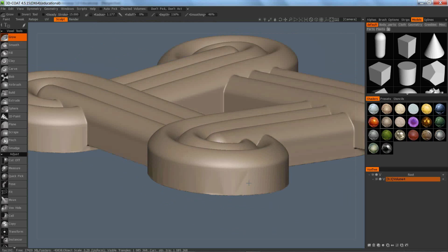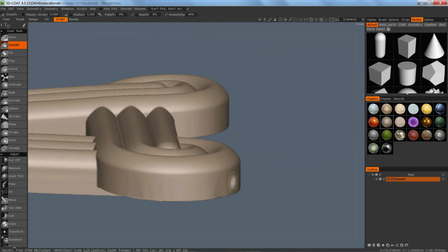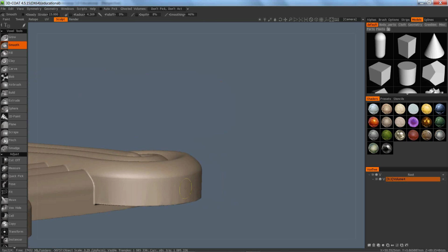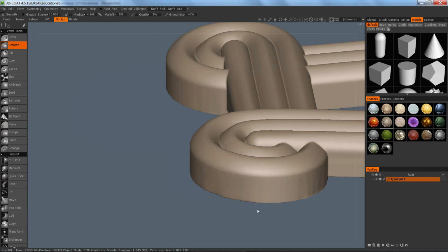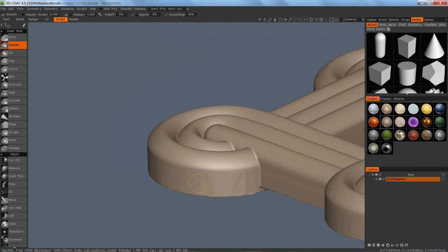One of the beauties of 3dcoat is that it does have a way for you to get a very solid object, a guaranteed solid object. While the brushes have the same names, they behave differently between surface and voxel, and this is something that a lot of people hate about 3dcoat. Other people like, because it's like they get twice as many brushes. It is confusing, but the smooth brush has less impact in voxel mode than it does